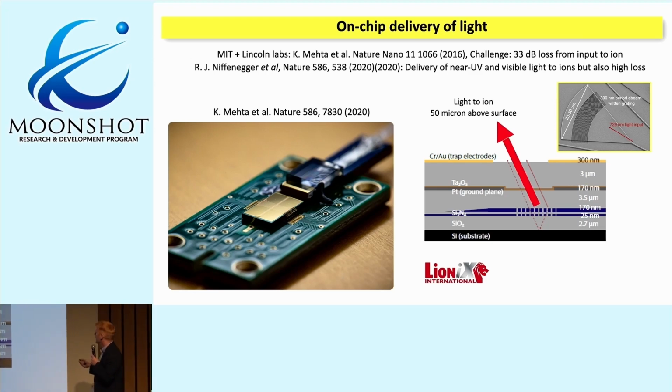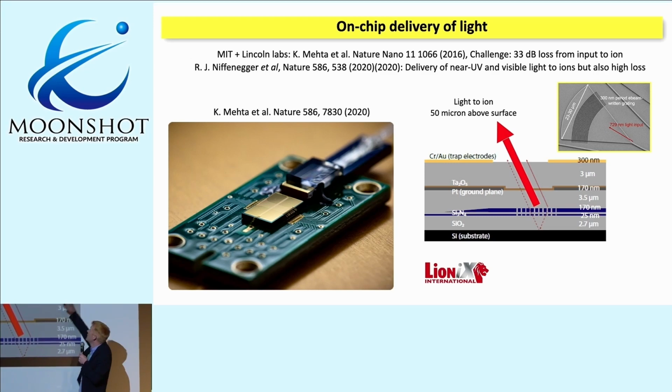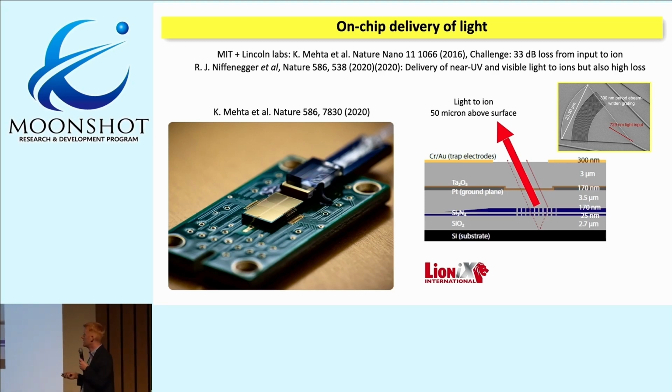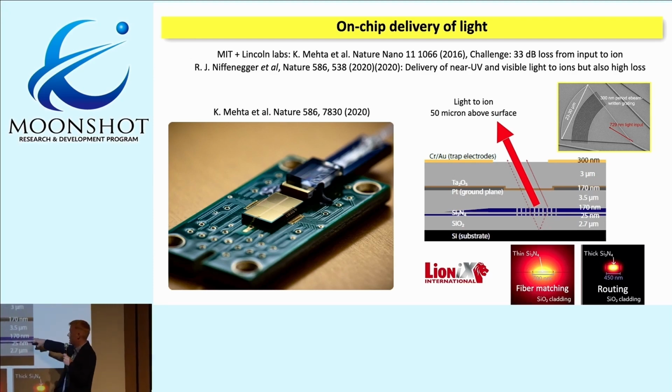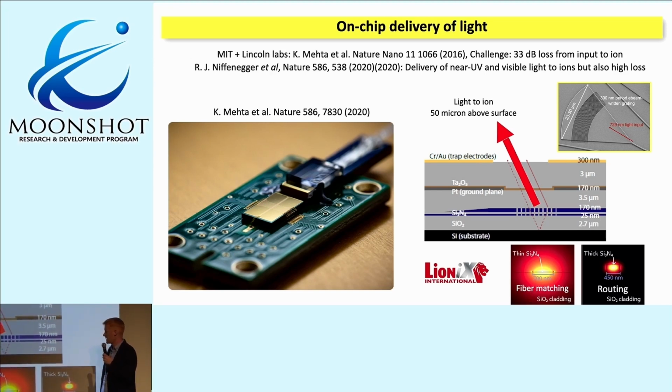So, how does the light get there? Well, there's some structured patterns in the silicon nitride. These form diffraction gratings. The diffraction gratings are focusing gratings, and that takes our light to a sort of 3 by 7 micron spot, in this case, above the chip. The other thing you'll notice if you look carefully is that there are a couple of layers of silicon nitride, and actually that's a process which LioniX had developed prior to us getting to them.